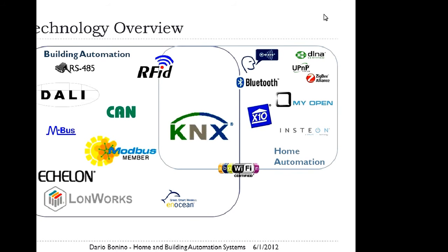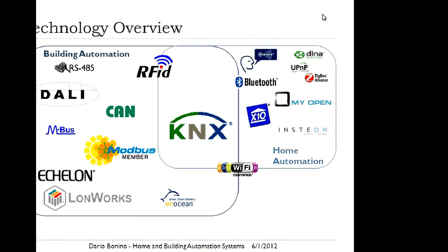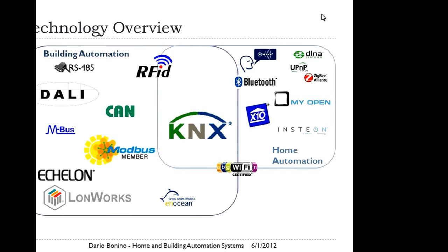community. On the other side, there are some home-specific protocols and technologies which share the same, let's say, objectives, but they tackle the problem in a different way so that less skills are required for installing the system, basically. So the My Open system, for example, is coming formerly from BTicino, now from Legrand, and only requires electricians to install the elements because the configuration, as we will see, is based on some kind of electrical connectivity, electrical connectors put on the back of devices.